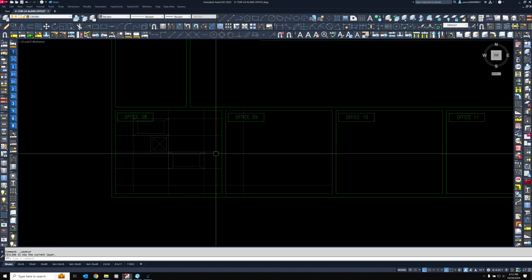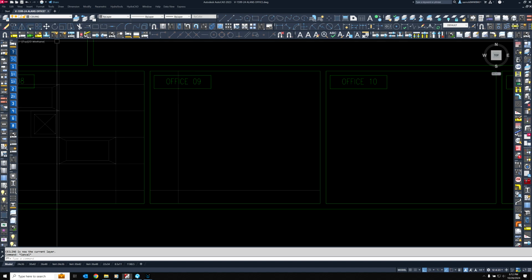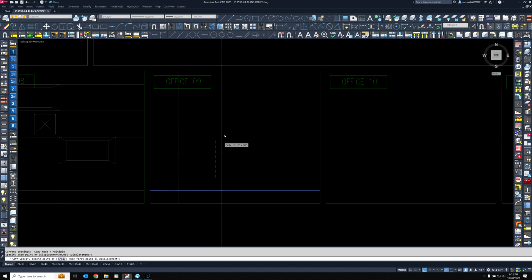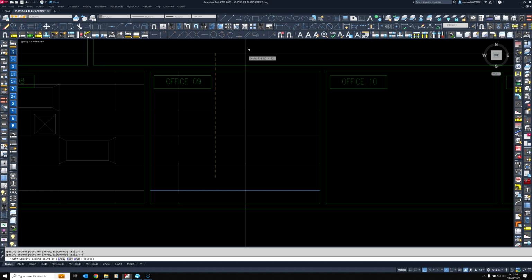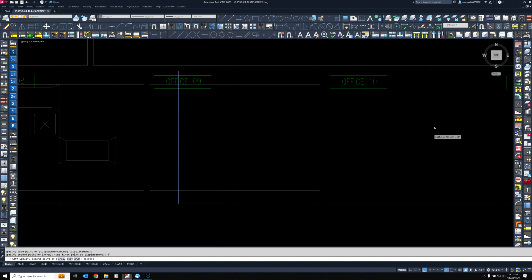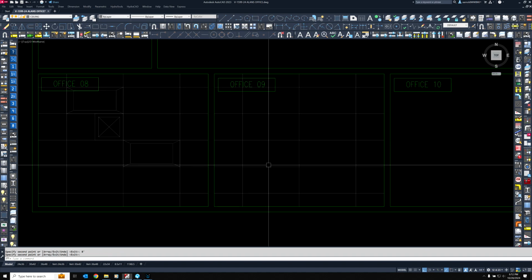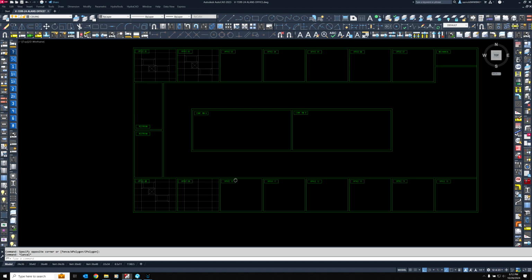But I want to make sure I'm on ceilings. I'm on ceilings. We've started putting this grid in. We know it's 2 foot by 4 foot. So I'm simply going to copy those lines that are the length and the width of the room. It's 2 foot, 4 foot. How about, yeah, there we go. Couldn't see it. 2 foot, 4 foot, 6 foot, and 8 foot. So we've got the start of the tile that direction. We're simply going to copy and take the tile 4 foot and 8 foot, and now that room has its ceiling grid. Drop in lights, drop in diffuser, and you're good.